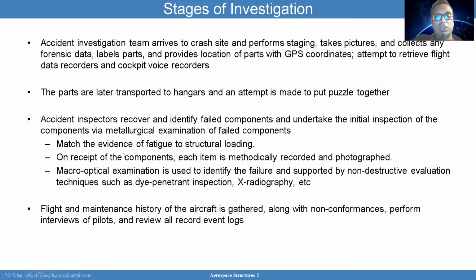You want to match the evidence of the fatigue to the structural loading conditions. Once you receive the components, each item should be methodically recorded and photographed. You also want to take a macro optical examination, and you want to make sure you identify the failure, and you want to support that with non-destructive evaluation techniques such as dye pen and X-ray.